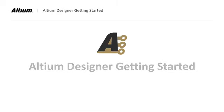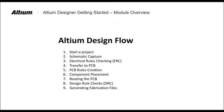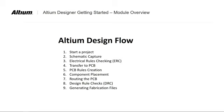Welcome to Getting Started in Altium Designer 19. We will walk through the design process, starting with a blank project, adding schematics and the default PCB. We will capture the design, and once complete, we will compile the design, performing the electrical rule checking prior to the transfer to the PCB for layout. Once layout is complete, run DRCs and then generate the needed files for fabrication and assembly.